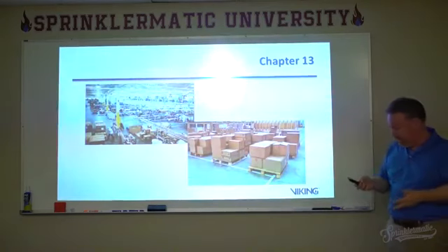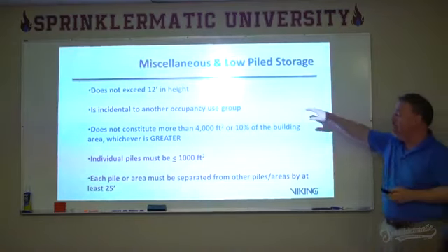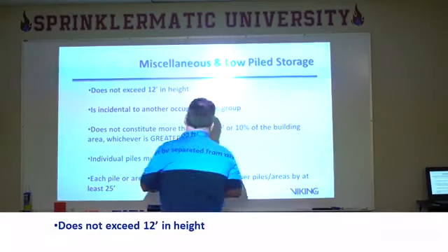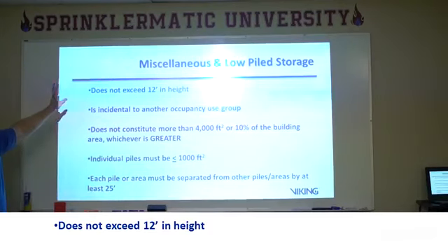So what do we do with it? What we're going to find is miscellaneous and low pile storage. First of all, it doesn't exceed 12 feet in height, because once it does, then we're off into the storage requirements, through chapter 14, 15, 16, or 17.